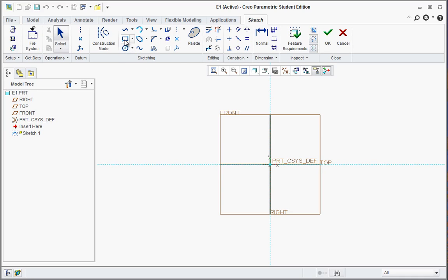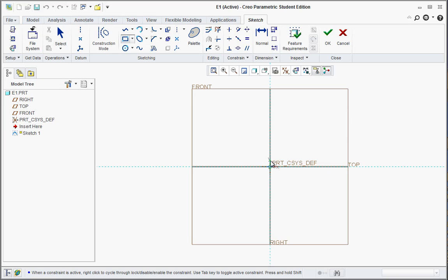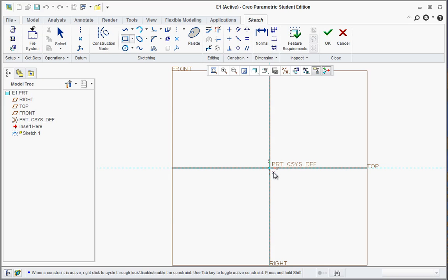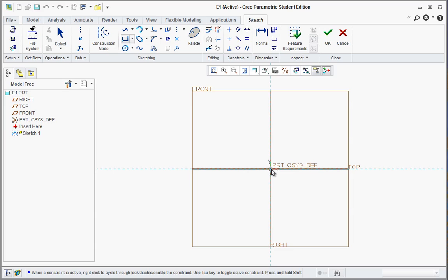Now, I'm going to go ahead and select the corner rectangle tool. Typically, when you see a little arrow to the right of any tool, you'll see that there's several other options. We just want corner rectangle. And glide up to the center, and you could zoom in and out with your middle scroll. If you scroll in and out, you can zoom up to that. Click and drag out